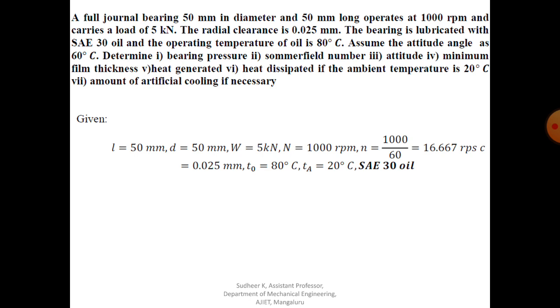If you use the Mahadevan data book, you will get kinematic viscosity in centistokes. To convert that you again need density and so on. So it is better to always go with the Lingaya data book. The one sheet is more than enough.